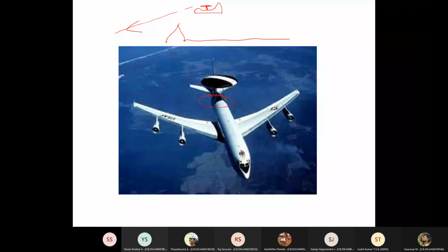It's going to be a nightmare because this pylon itself is going to act like a lifting surface. We don't know, like if the aircraft is inclined like this, so this pylon is also like this and it's having an angle of attack. So you have another force coming up. So a lot of problems apart from the drag also.